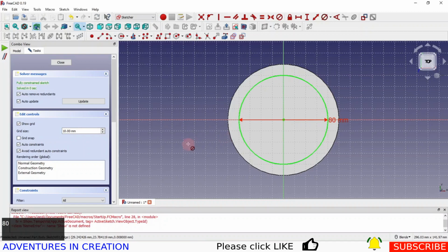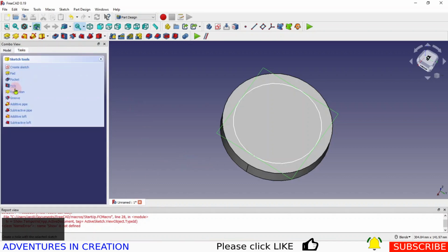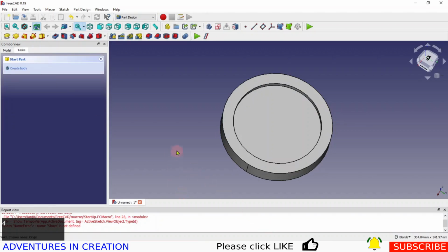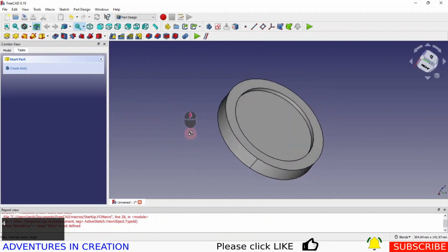Now, of course, if we wanted to, we could put these dimensions into a spreadsheet, and that would allow us to have those be parametric. We can just change them on the fly. But for this, it's very simple, so I'm not even going to bother doing that. And this is going to be a pocket. It's going to be a 4 mil pocket because that's how deep I want it to be. So I'm going to create a 4 mil pocket. That basically is my coaster.